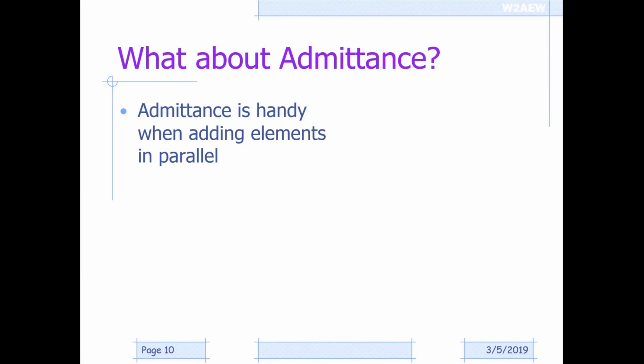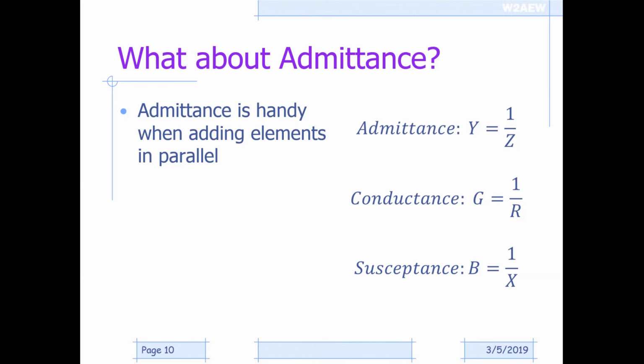Now, of course, everything we've talked about thus far is constant impedance. So what do we do? Well, admittance is really just 1 over the impedance, right? So that's pretty easy. So in a sense you say, well, conductance is 1 over resistance, and susceptance is 1 over reactance. But the reality is those two equations are really only true when the real component, the R, is 0. That's the only time we're really going to have that, because otherwise we have to take this complex quantity and invert it. And that's a little bit more complex math.